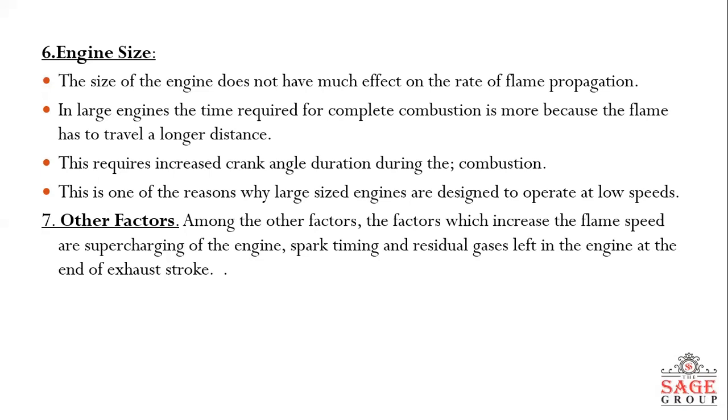Some other factors that increase flame speed are supercharging of engine, spark timing, or residual gases that are left in engine at the end of exhaust stroke. If we supercharge the engine, the intake pressure will be increased, and during the compression stroke, we can achieve a high pressure and temperature. So it will reduce our initial preparation phase and also speed up the second phase of combustion.